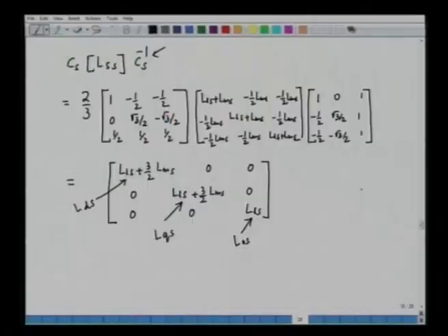Okay. So, we have already seen that this is the inductance matrix of the stator in the dq model, which does not have any off diagonal terms, and we also see that LDS equal to LQS, we can say that is equal to LS, the stator inductance of the d and q axis. So, that is equal to LLS plus 3 by 2 times LMS.